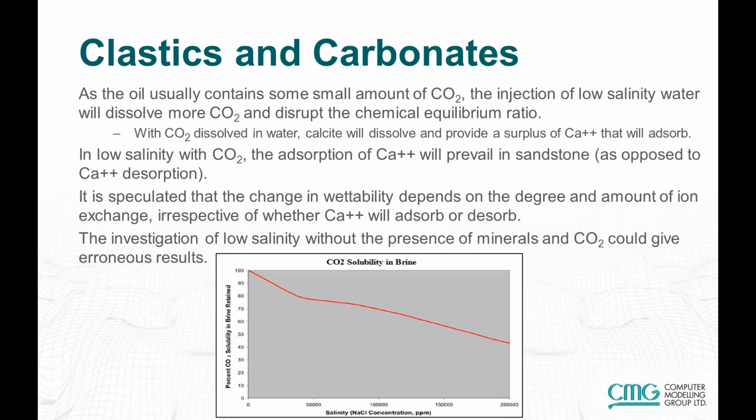Now, with both clastics and carbonates, CO2 seems to be a very important part of the whole process. And usually the oil will contain some small amount of CO2, maybe 1 mole percent or something like that. Then when you inject the low salinity water, what will happen is that the CO2 will partition more into the water. So you see down here at the bottom a plot of the CO2 solubility in water.